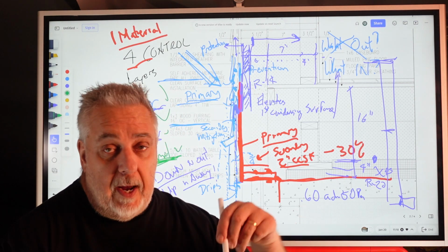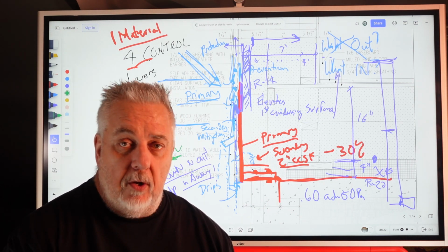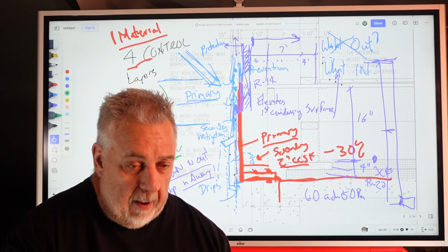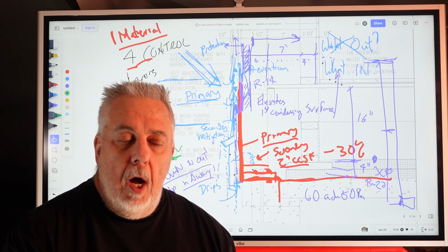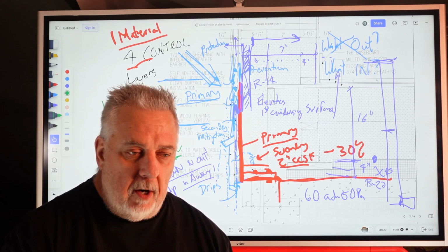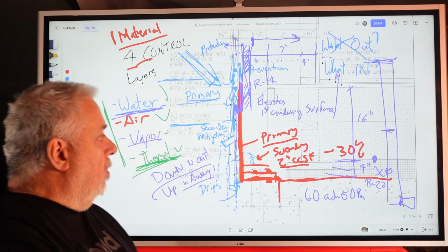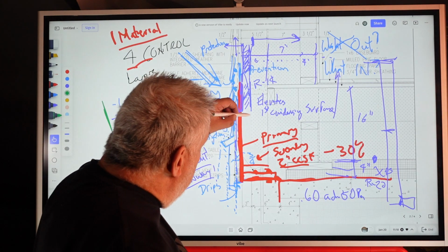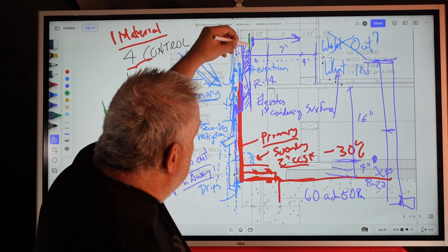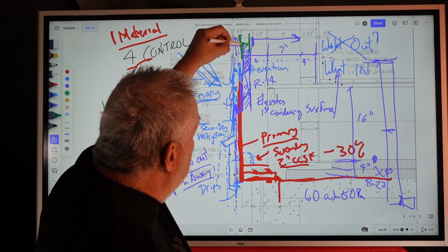In this case, we had to deliver a passive house, so we had to meet a certain level of insulation that would meet a certain energy requirement per square meter of surface area on this house. So we had that, but we'll run through. We talked a little bit about it. We have our 2 inches of closed cell foam here.